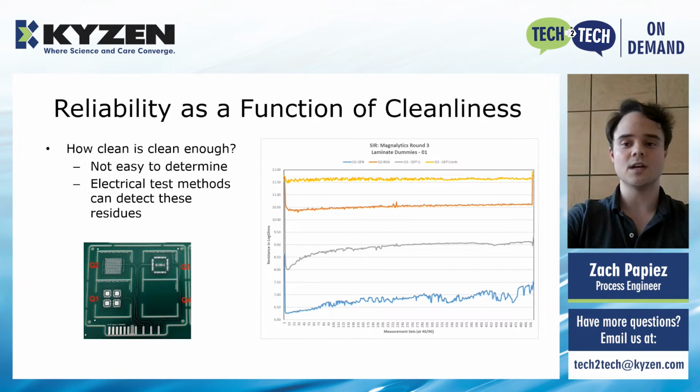Understanding how clean is not as easy to determine, however. Many SIR tests in different conditions are likely required to understand an upper limit for board cleanliness for your process. Likely more testing is then required to be run at an acceptable condition to verify the consistency of said cleaning process. Having said this, it would be impossible to accomplish without SIR's ability to detect the active residues left over from an inadequate cleaning process.